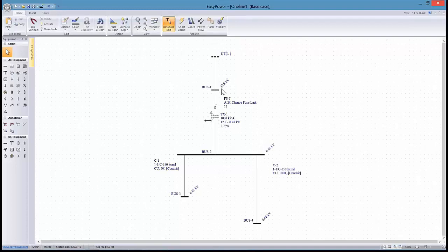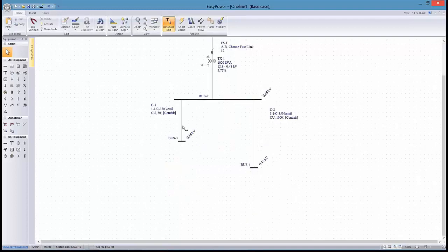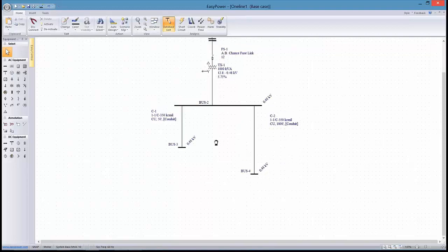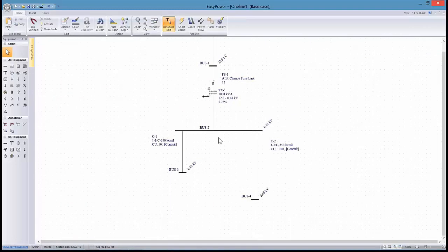The utility comes in at 12.8, with a 1000 kVA transformer, and he has a 480 volt distribution. As far as his model, he only has two cables, one a very short one at 50 feet and one a very long one at 1,000 feet. He said, let's just disregard the pumps connected to these cables. I just need to label these particular intersections.